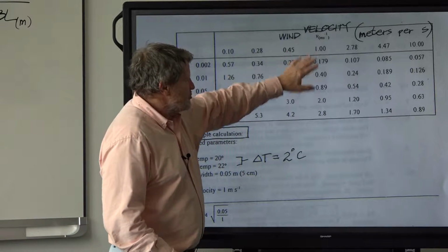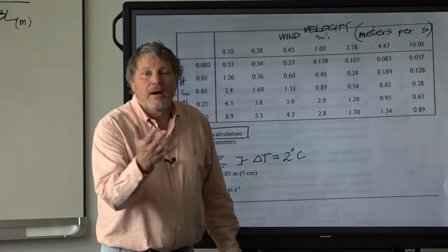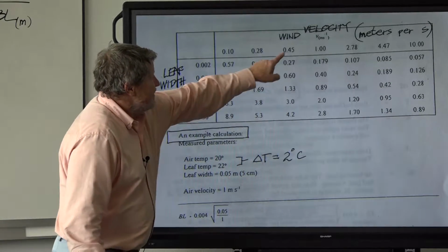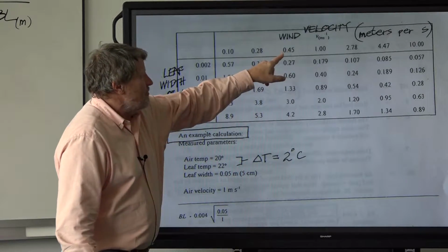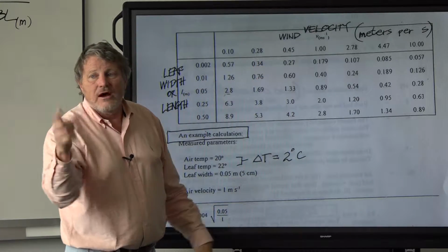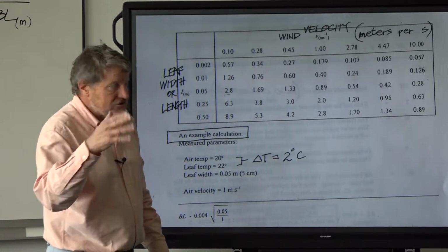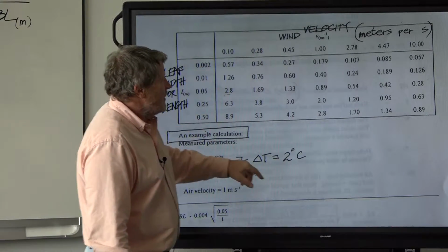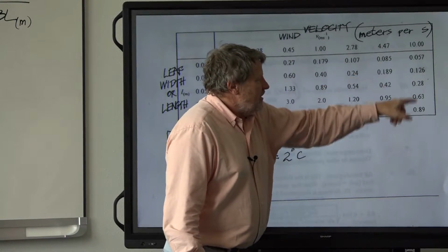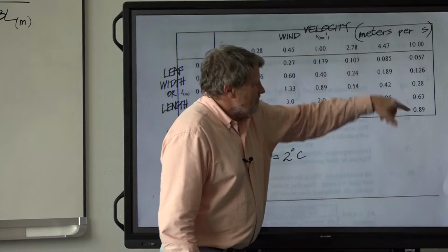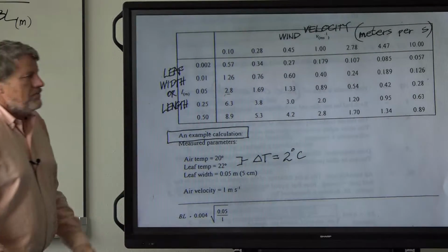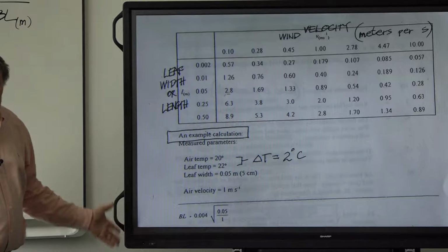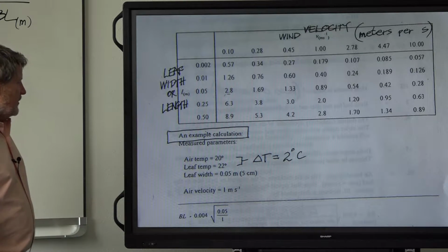And cup anemometers, as you all know, it takes somewhere around 0.4 meters per second to start turning the cups. Depends on the instrument, but this is very still air. Now we get up to 10 and it's really breezy, and all these numbers are small, so leaves are going to always be very close to the air temperature when the wind is blowing because this gets tiny.